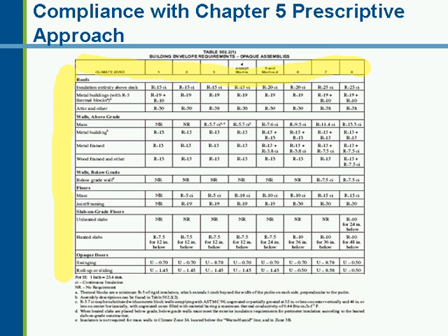There are some terms used in the table called CI, and CI, as in right here, is considered continuous insulation. So an R15 continuous insulation would be insulation not broken up by framing members. This is similar to what was in the 2003 IECC, but that normally applied to mass walls where you could install insulation continuously and get credit for that. There are sometimes some requirements that were in metal frame walls in the 2003 IECC that also required insulation between frame walls and also continuous insulation. So it's the same concept carried over into this table. It's just called something different.